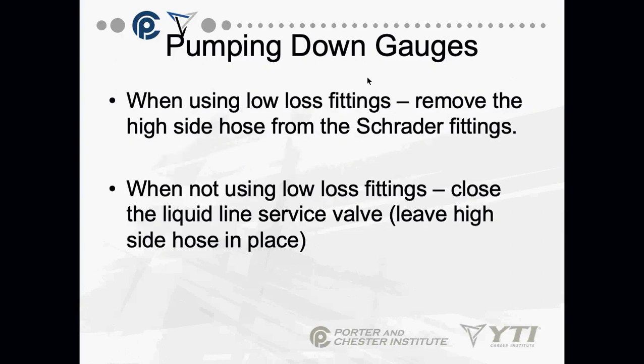Okay, now, everyone's gauges or tool bags come with low-loss fittings. There are two little brass fittings in your tool bags, and I know I have some new students on here who haven't gotten their tools yet. There are two brass fittings that screw into your gauge sets. Schrader core fittings.